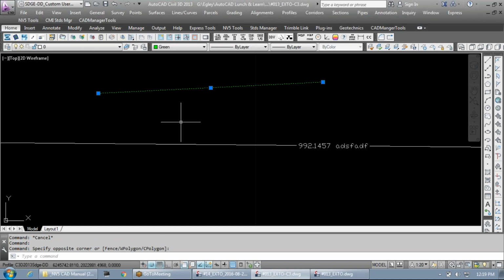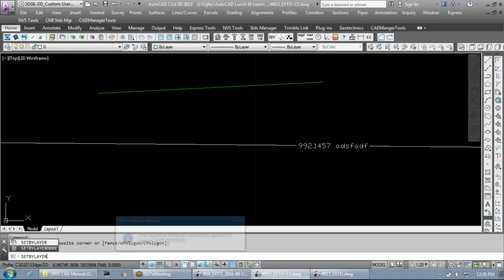If you run across a file that has a bunch of things set like this, one of the most powerful commands in all of AutoCAD, in my opinion, is set by layer. I used this command almost weekly at my former company. I'd receive files from an architect, and architects are infamous for hard setting colors, embedding blocks, and that third nested block has a line that's hard set to red, or color 10, right? The last thing you'd want is to have something plot color 10 in palette A, right?